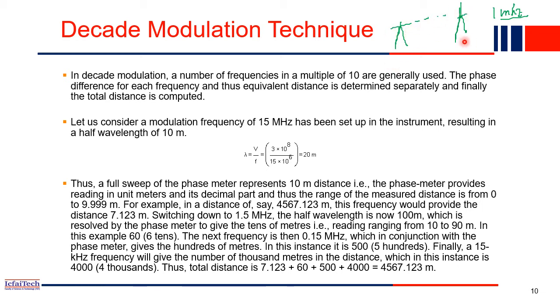Next time, the same measurement it will take with maybe 10 megahertz, and again it will measure the distance. Then 100 megahertz, like that 5 or 6 different signals with different frequencies it will send and observe. So like that, multiples of 10 we use, like 1, 10, 100, 1000 megahertz. Multiple signals we send, and every time we measure the distance between A and B.